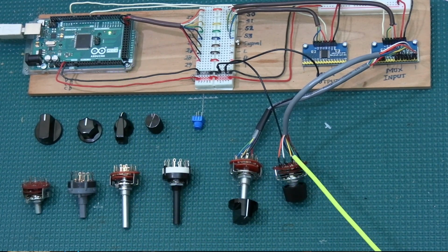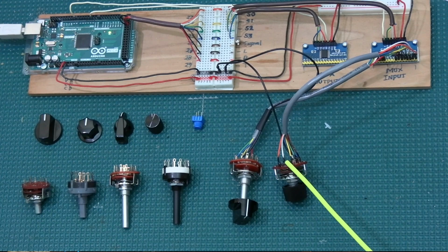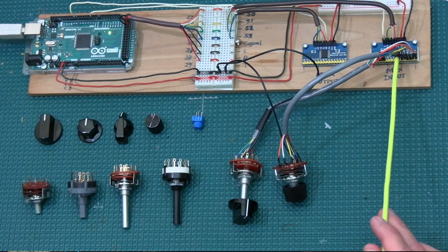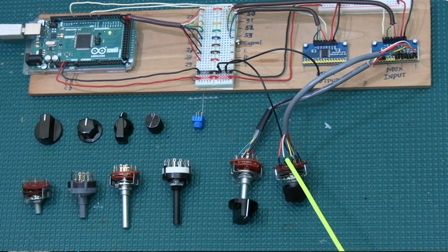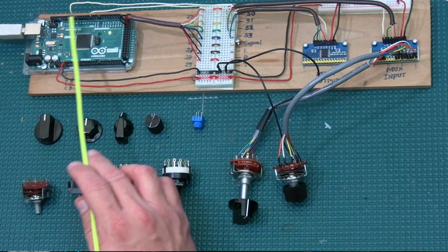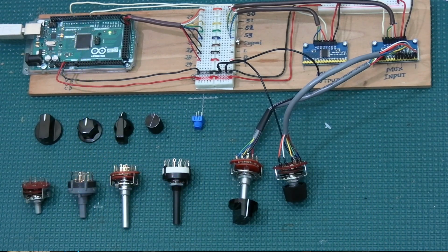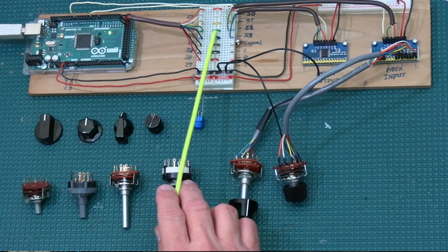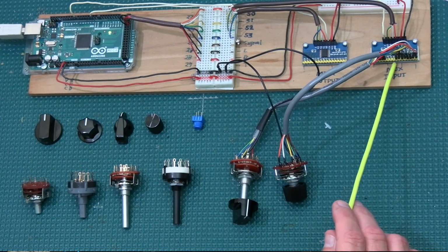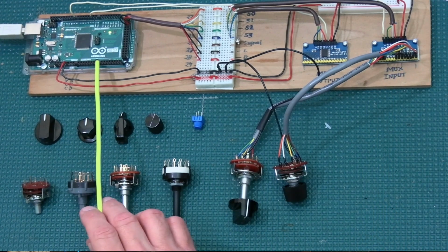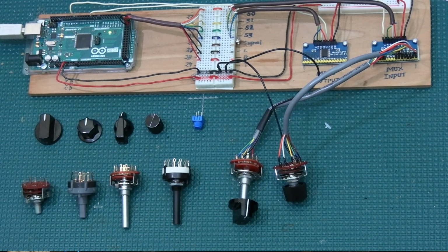But then again, if you have, let's say, 2 of these, you're already going to be taking up 16 inputs on your Arduino. When instead you can use a multiplexer and you can connect 2 of these and use all 16 of them, but only use 2 pins on the Arduino. So like always, I'm always going to recommend that you set yourself up a data system bus distribution, and you're going to use multiplexers to do it. That way you can use a ton of inputs without wasting all the pins on the Arduino, which you might need for something else later.